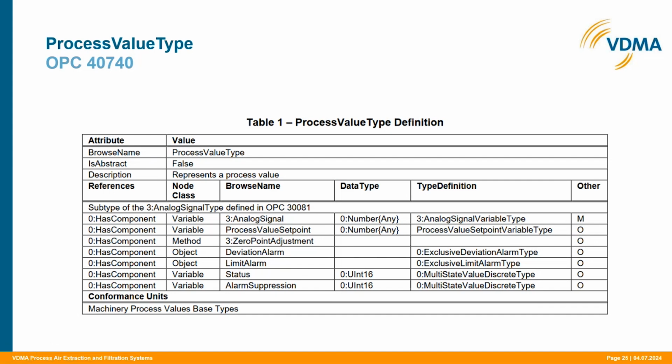And this is, for example, used in our filter units to say that the threshold of differential pressure that is used to describe the filter filling rate is reaching a set limit, and this limit may be used to replace the filter element inside of the device because it's full of dust or full of particles. And so I just want to make clear that this was one of the main discussions that we had while we were developing our companion spec, and this way of describing values helped us greatly.